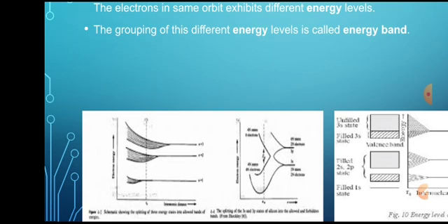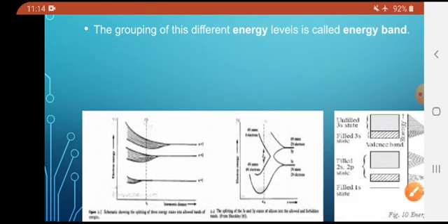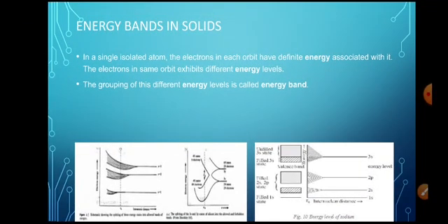In this region, shown by the dotted line, no energy gap exists, as the upper and lower energy states get mixed. Finally, if the distance between atoms decreases further, the energy band again splits apart and is separated by an energy gap. So, the total number of available electrons, 8n, has been reapportioned between the two bands, 4n and 4n, in the lower and upper bands.